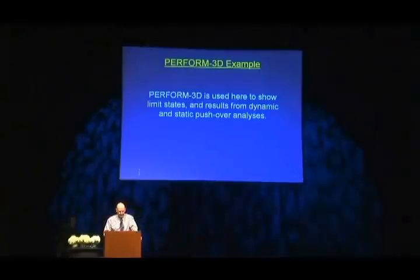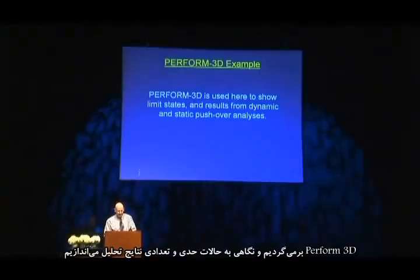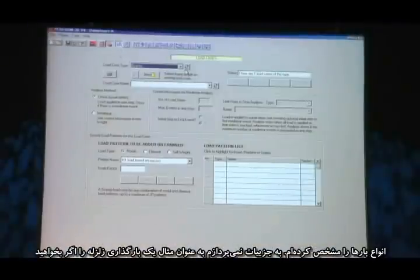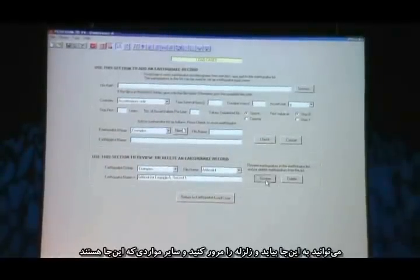So I'm going to go back here now to Perform 3D and look at limit states and a few analysis results. This is now getting into the analysis phase, and there are a number of things here. I can specify load cases, and I'm not going to get into any details here, but for example, here's one of the earthquake cases, and if you like, I can come in here and review the earthquake and a bunch of stuff like this.